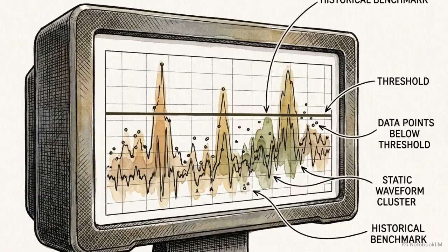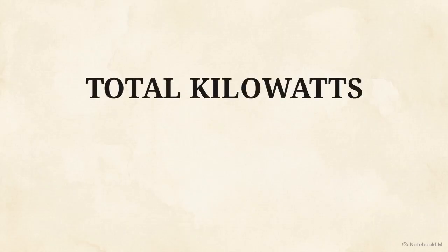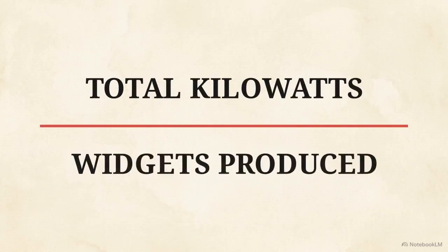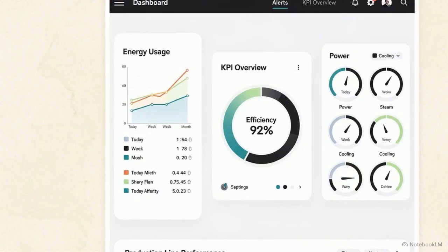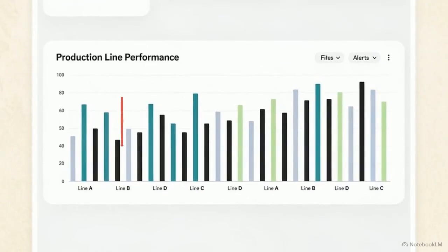Once the data is gathered, we reach step 4, identifying existing performance by establishing strict current benchmarks. Raw instrument readings mean very little on their own. To be useful to management, that energy data must be normalized against production variables. This dashboard tracks specific energy consumption, measuring the exact energy required to produce a single unit of output, to provide a definitive benchmark. By analyzing the load factor, auditors can immediately pinpoint poor utilization, unnecessary standby loads, and the cost